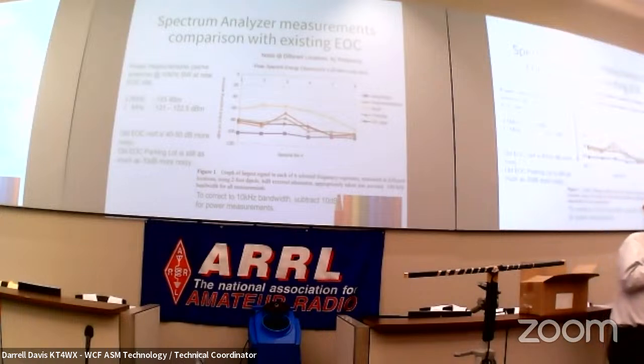Normally far field noise goes down by the square of the distance, and that's not too fast, but near field noise goes down by the cube or the fourth power of the distance. So near field noise from a radiator is much easier to get away from. And what we found was if we went into the adjoining lot, which the county then bought, and put our antennas up in the trees about 75 yards away from the building, we got down to acceptable numbers. And so that's what we had to do.